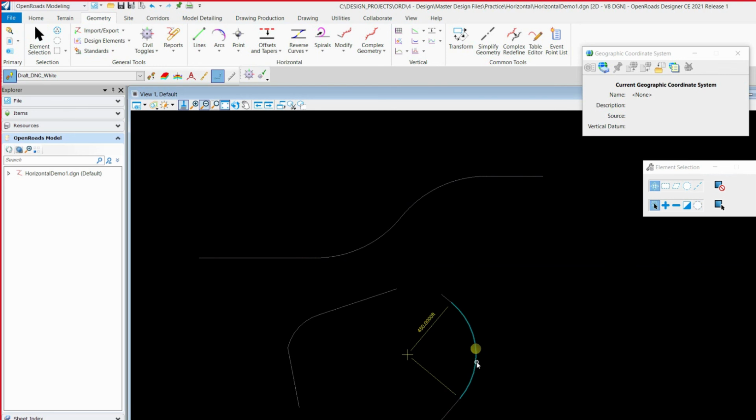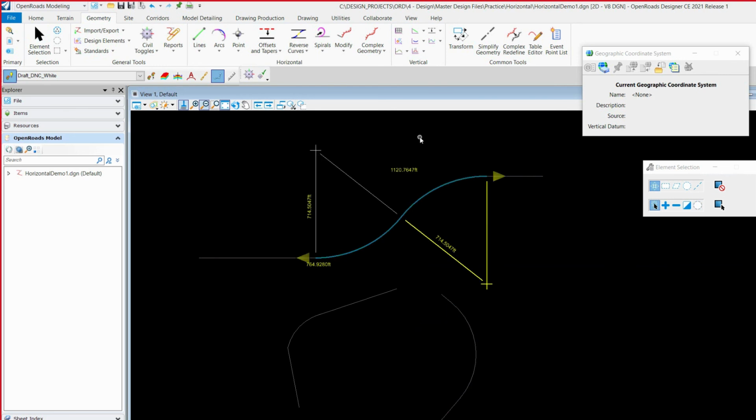The arc between elements here will only give you the radius, but with this one you get several different inputs, and you can go over here into the properties tool, and you can select the start offset, end offset, the back ahead radius. So you have a little bit more complexity, but it gives you more control. So I thought that was pretty neat.